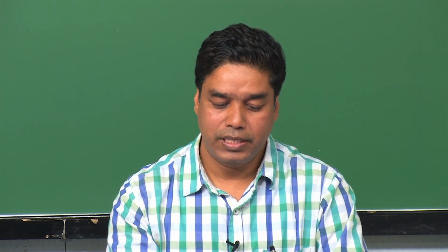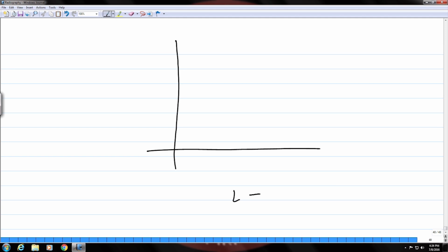Okay. So, generally the sample to source distance is kept at 1 meter, because this is convenient to use when you convert the exposure time for some other distance.